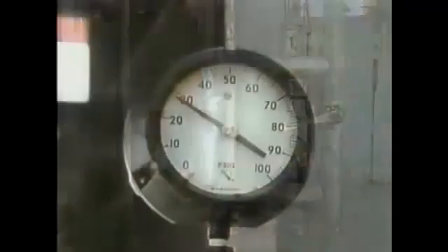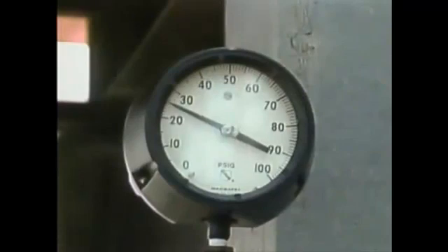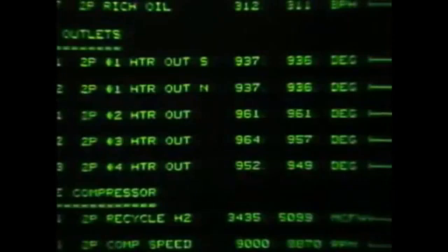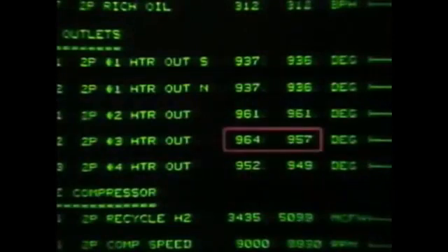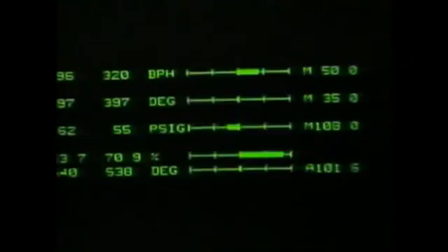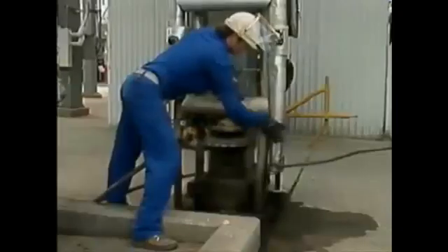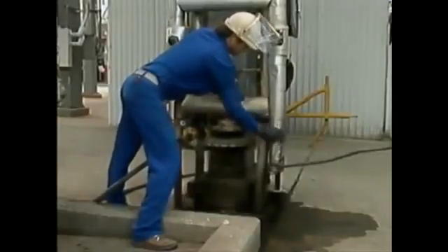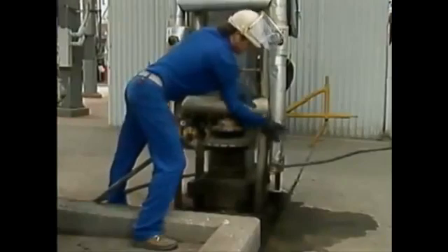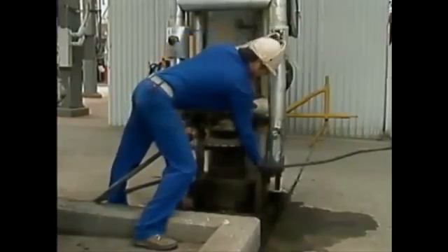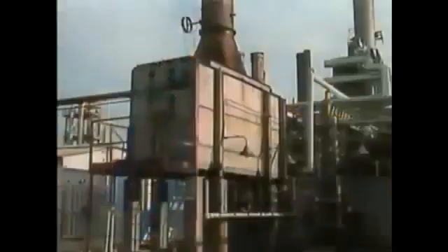If this happens, the fuel header pressure may decrease since the ice restricts flow in the fuel lines. Because of the reduced flow, eventually the process fluid outlet temperature will also decrease. In response, the fuel control valve opens up, trying to send more fuel to the burners. Some plants handle freeze-ups by injecting steam into the fuel lines while the furnace remains in operation. The steam thaws the ice.